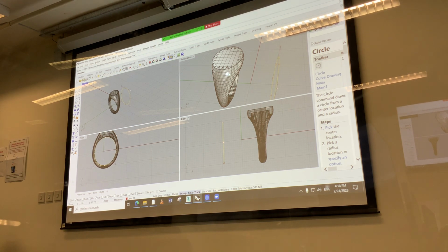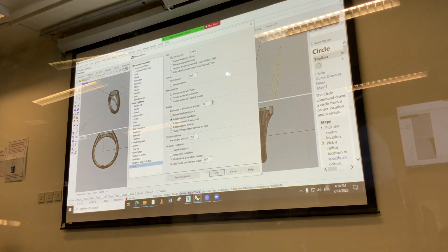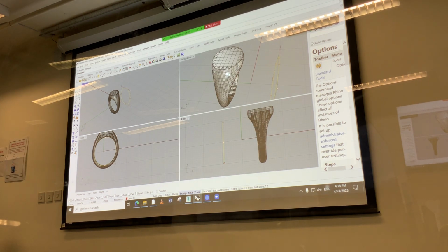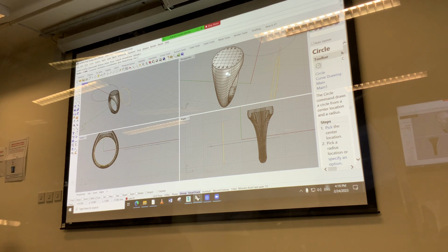So go quickly to your settings. Check what the units are. It's millimeter. I think it's precise this time, so we should keep it in millimeters. All right. So, little ring here. Diameter is switched on. So this diameter, then let's make a ring that is, say, 18.